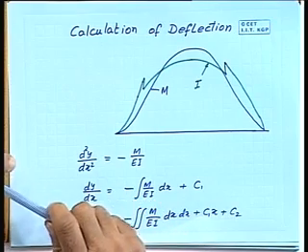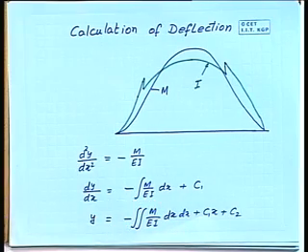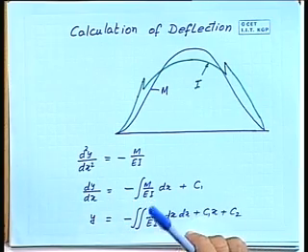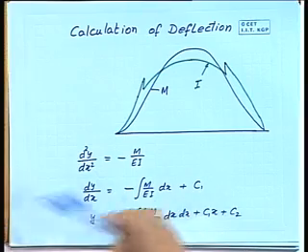For all practical purposes, we consider that the ship is made of one single material, and therefore E is constant all through. We may use two different steels, for example, mild steel and high tensile steel, but if you see the elastic properties, you will find that more or less E is constant. It is the tensile strength which varies in the two materials, but E is more or less constant. So, even in such a condition, we may assume that E is practically constant.